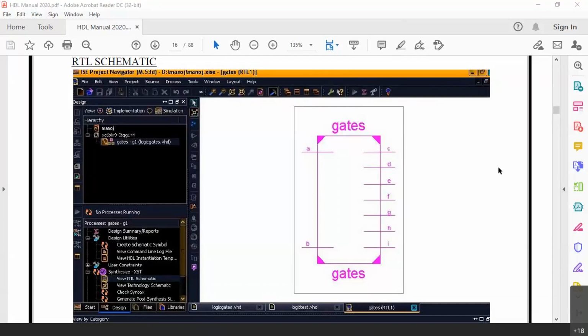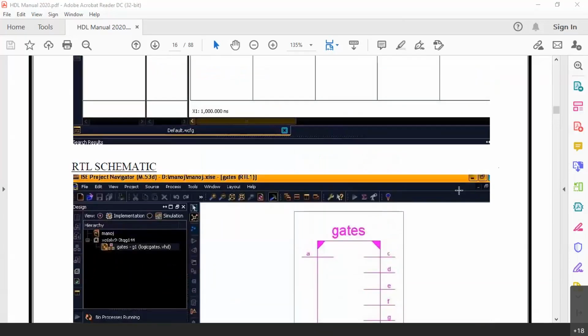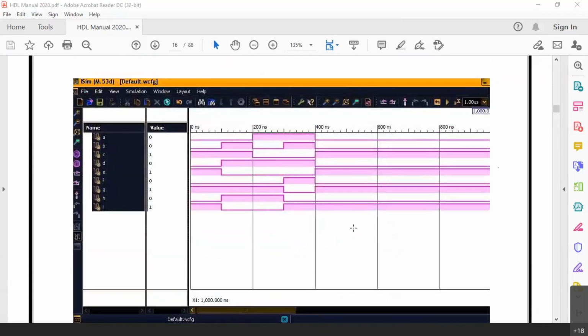But non-synthesized HDL is required for us to verify whether the code is working or not, to verify the functionality. So whatever you saw right now, this is the simulated output. In the sense, without actually getting the code implemented on a chip or FPGA, we have simulated the code and we have verified. That means code is going to be mapped into the hardware, that we are sure. But right now synthesis has not happened and the code is not converted into hardware. That process is called synthesis.